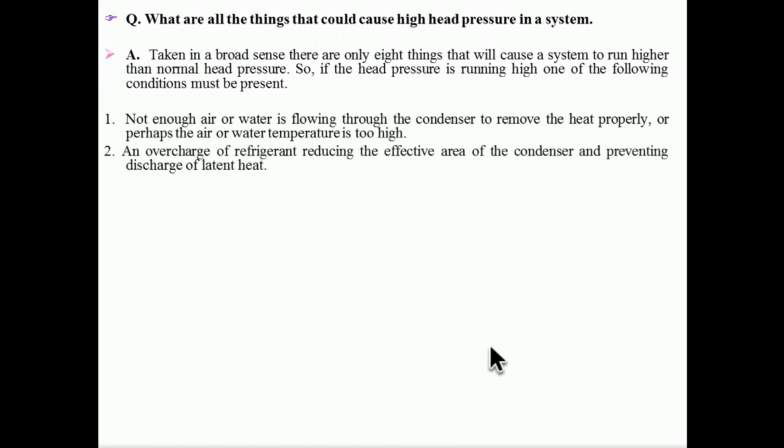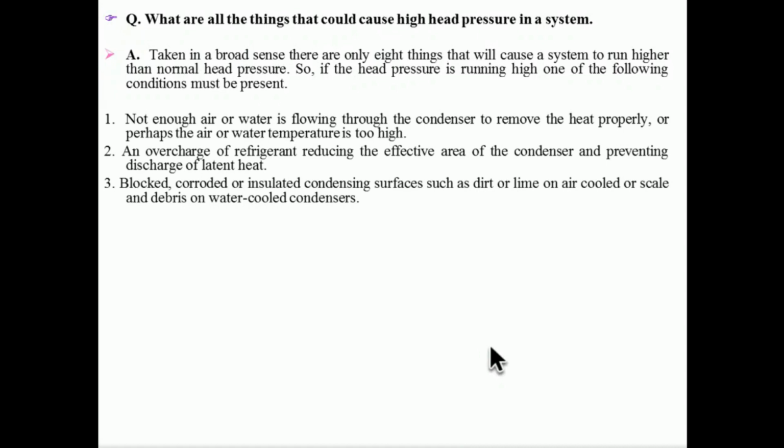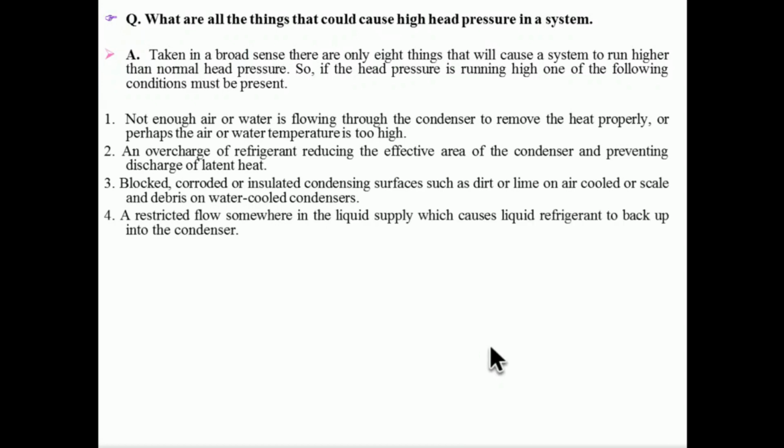Overcharge can also increase the high head pressure because it is occupying the condensing space. Blocked or corroded surfaces, that means basically scale inside the water-cooled condensers and complete dirt on the air-cooled condensers, can increase high pressure. A restricted flow is going to back up the condenser space, so that can also lead to high pressures. And non-condensables, that means we should have only proper true refrigerant gas. Anything other than that, any inert gas, is going to give high pressure because it's not condensable.